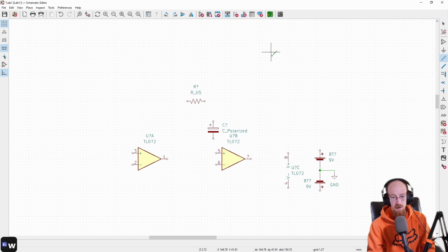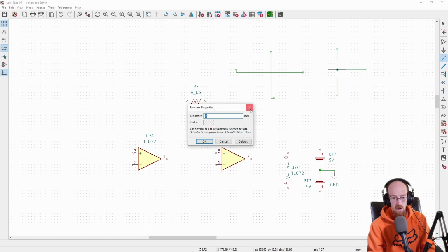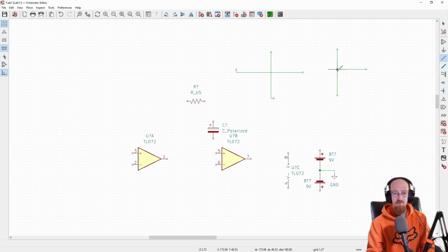A brief comment about wires. So let's say that this is like a wire. If we have a wire go like this, these wires are not connected. If, however, our wires go like this, these wires are connected. I see students sometimes try to do what we sometimes do when we're handwriting, sort of the little up and over. This just is confusing and messy, and it's harder to do in KiCad. So just stick with the dot convention.